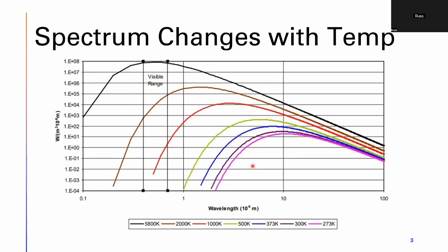So how a greenhouse works, how your glazing works, your glass or your polyethylene or your polycarbonate: the higher frequencies come into the glazing. It'll warm up the matter in the greenhouse. And that matter being at a lower temperature, like the 300 Kelvin range versus 5,800 Kelvin for the sun, that lower energy will emit a different spectra, the infrared range, and that'll bounce off your glazing, and that's how a greenhouse warms up.